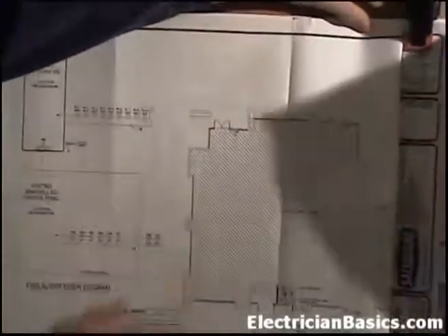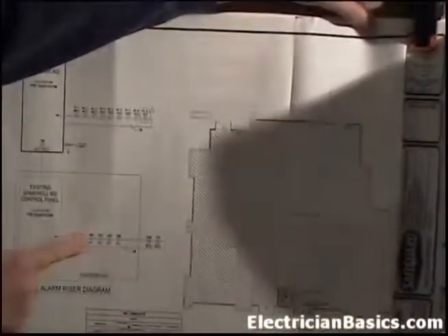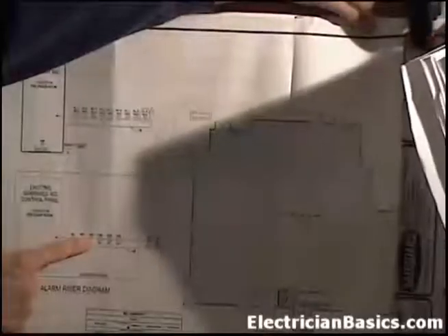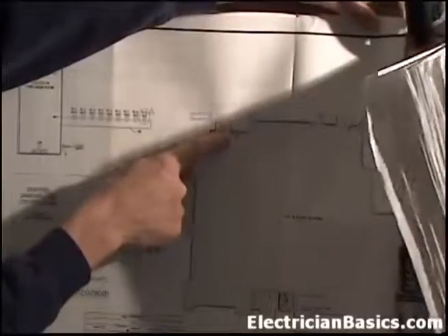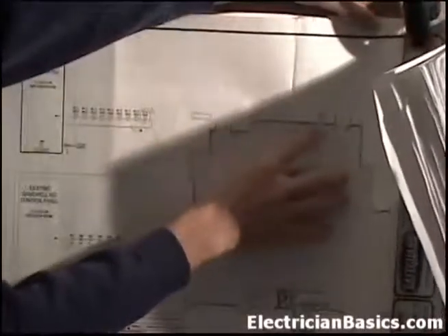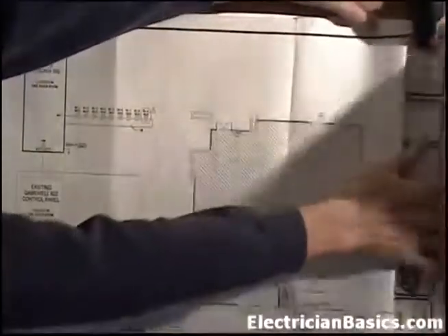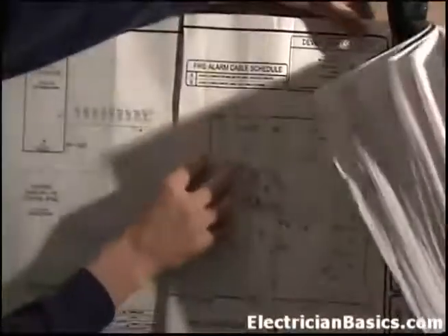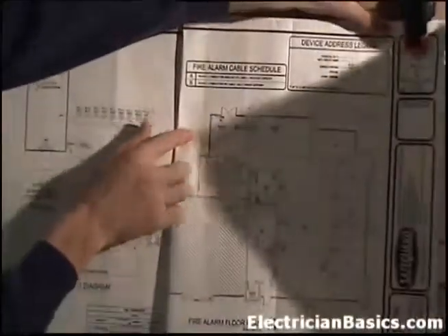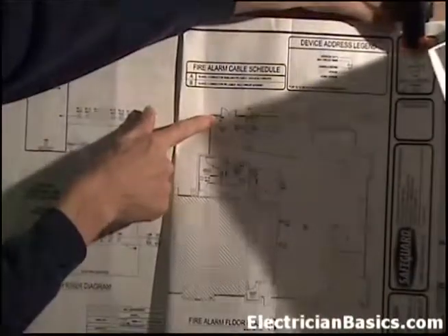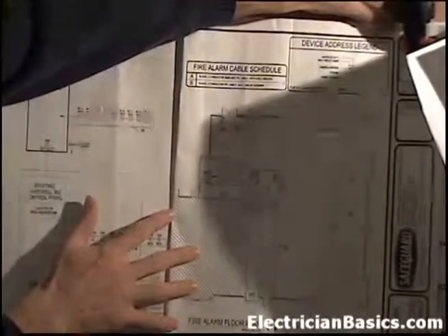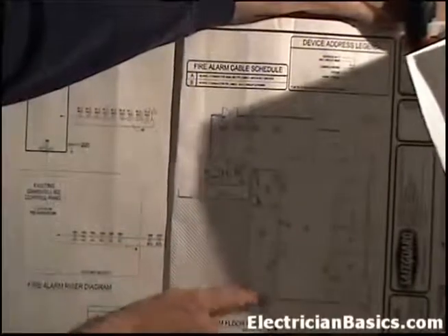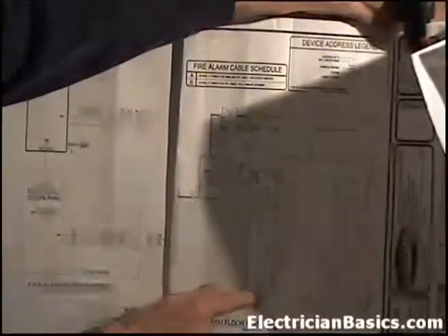Okay, let's hold our print out there. Our next one here is this 1004, and that was an addressable manual pull station. That's at this door here. And then 1005 was out here. Okay, now let's go to 1006. That's in the scope of our work, and that was here by the front door. Now remember, we had a note that said we were going to relocate that, and we covered that earlier. Now also we had a note saying we were going to have another one by this exit door.